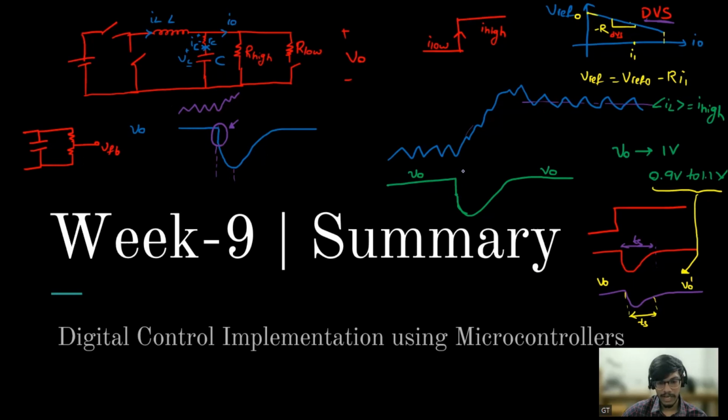Because the inductor is not sufficiently charged in this region, it takes some time. So the capacitor has given instantaneously, and the capacitor has delivered that power, and the inductor does not have that power to give to the capacitor either. So it takes some time for the inductor to charge, and till that point the capacitor will still discharge. And at some point of time, when the inductor is sufficiently charged from the input voltage, then it will deliver to the capacitor, and slowly it will give to the load as well.